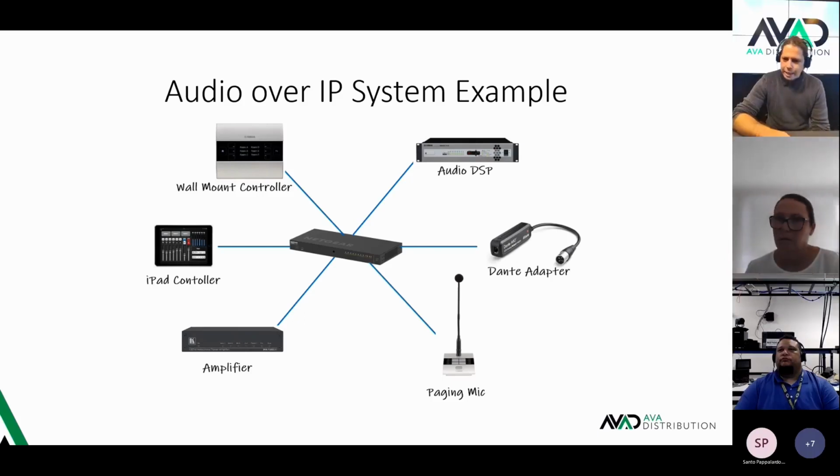Okay, so our networked amplifiers as well. What's great in this scenario is if you're doing a distributed bell paging system, you can link your amplifiers around a school and drive your speakers off the amplifiers locally. So you can connect them all via Dante protocol into our switch. We can distribute those switches if need be around the campus, and we can all put them on our own controlled VLAN. We can have our controllers as well integrate into our network. So it just makes the connection side of system design so much easier.